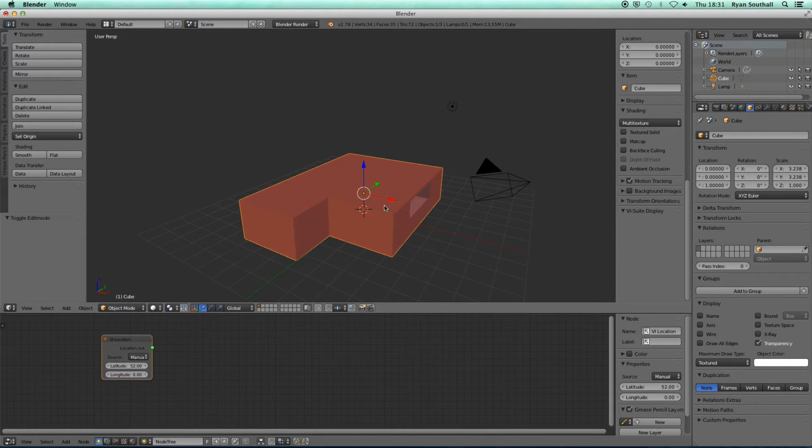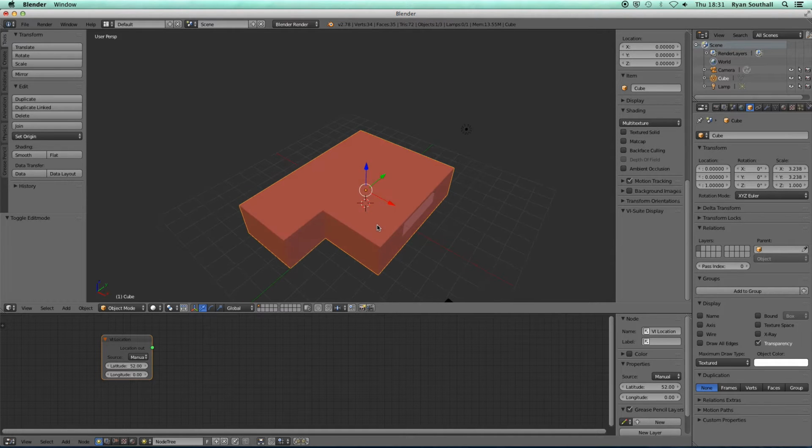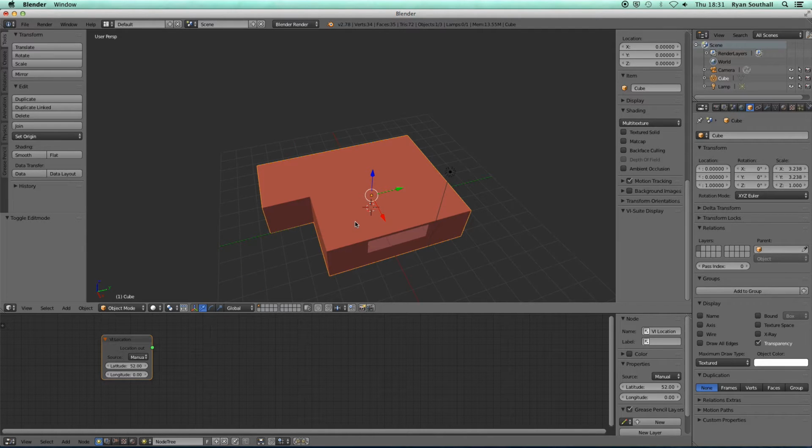So I've got these brown walls, I've got some windows, but I need somewhere to sense lighting level. And this is done in a very similar way to the shadow mapping video I did last time, in that any geometry within the scene can be sensing geometry, and we can specify the vertices or the faces of that sensing geometry to be calculation points.